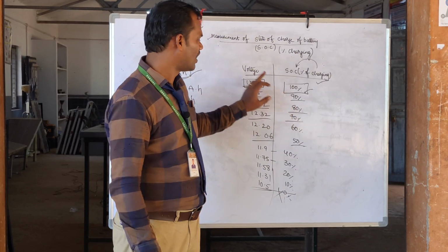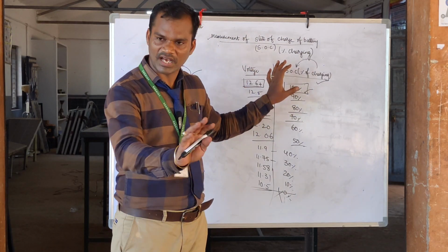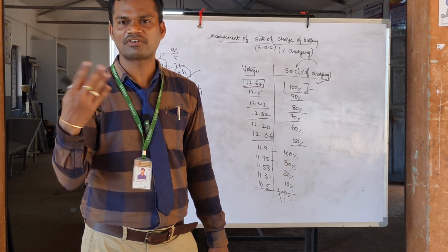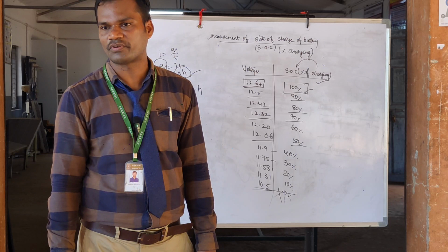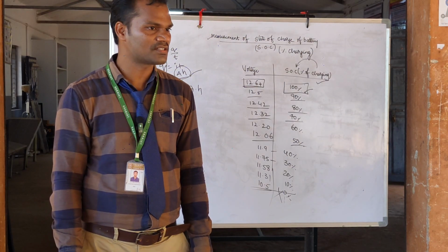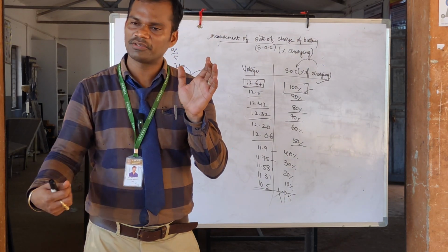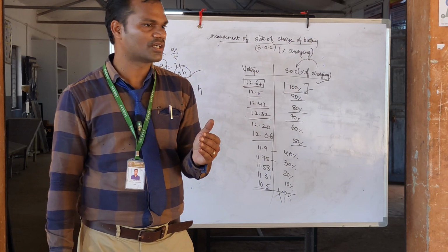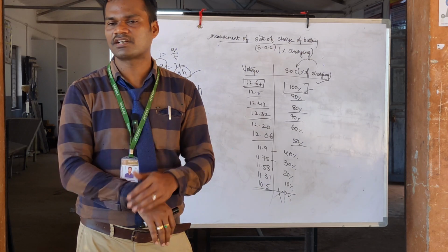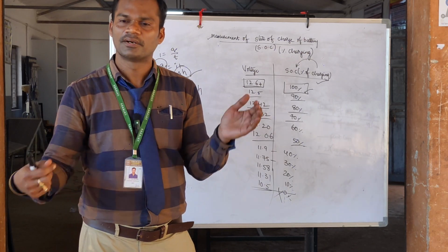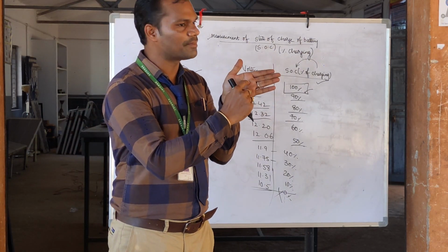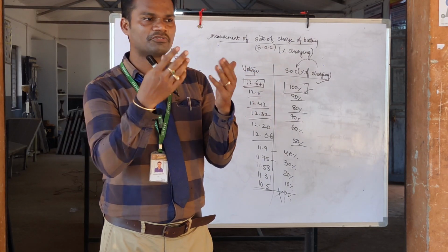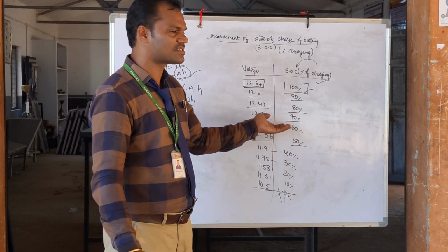State of charge indicates how much voltage is available and how much charge is available. Now it is full, but if you connect a load, it may discharge in less than 1 hour. I can say the health is very weak. If you buy a new phone, when you charge it, it will have full charge and will last a minimum of 1 or 2 days. But when it goes to 2 or 3 years, the life cycle is already completed. The indication still shows 100%, but within 1 hour it will discharge. It is saying that the battery is weak.